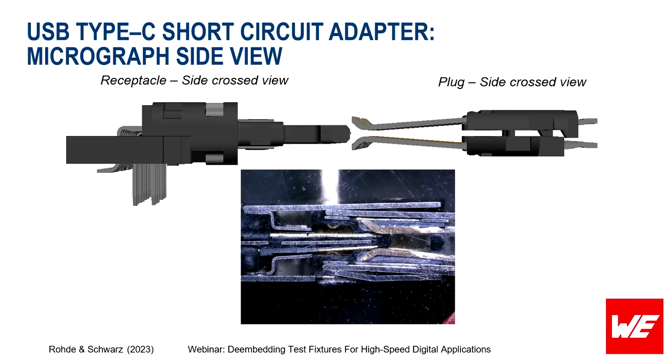In the middle, when you see this side view, you can see how the plug contacts to the receptacle. The plug normally contacts to the receptacle by the spring clamps, and when you only insert a cable connector or the shortcut device, then you need an additional function. And you see it on the side view in the bottom.